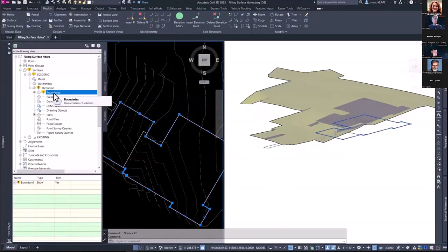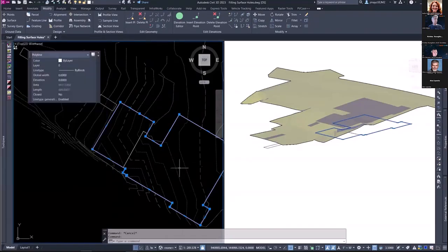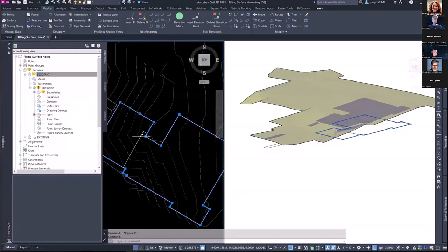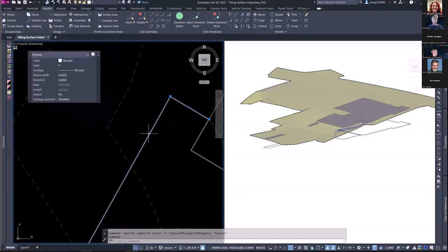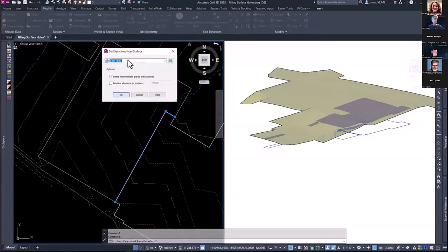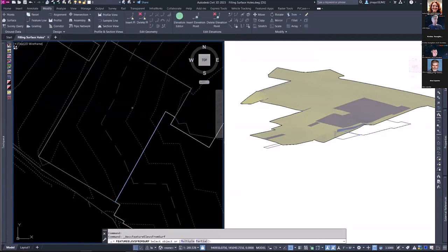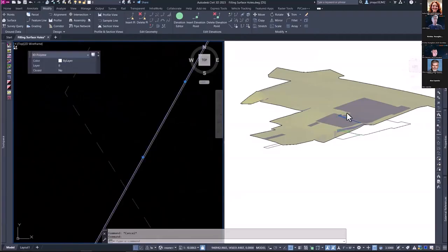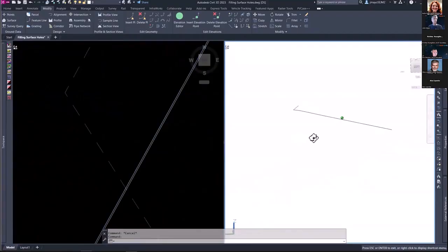Now this is in our surface, e.g. demo. And because I just performed that operation on it, I removed it as a boundary. And that's good. I want that. I don't want to rebuild yet because I want elevations inside here. This is the dividing line. And I'm going to use features from elevation, or feature elevations from surface, and get elevations from the demo surface, the one that goes through here. And you can see that comes up to grade where the demolition surface is.